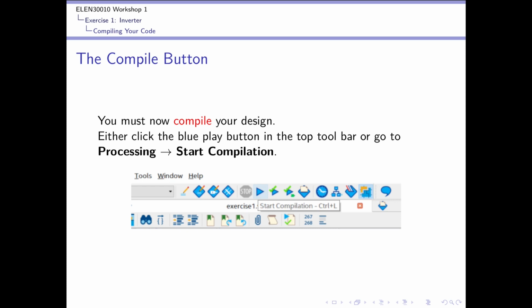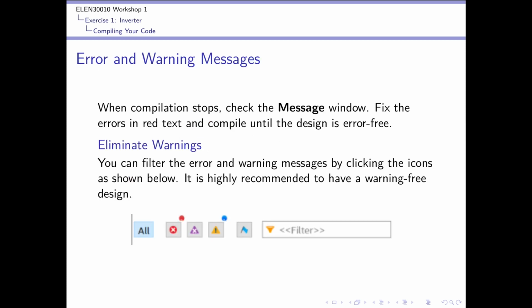And since the logic gates are actually lookup tables, it actually has to configure the lookup tables to implement the logic gates that we want. So compiling the design is doing all these things. It's working out how to build the design and how to lay out the design and how to wire up the design, all inside the FPGA.